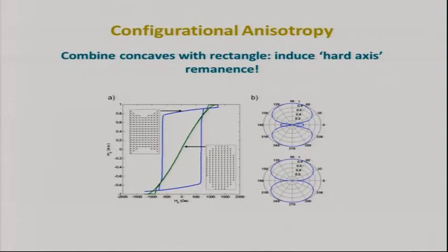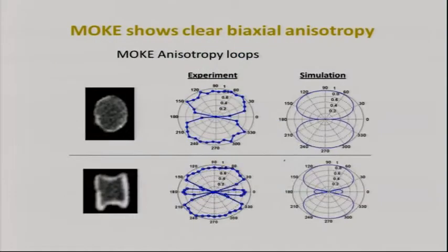Note that this is micromagnetic simulation. Note the steep switching threshold for putting the magnet right at the top of the barrier there. That is represented in this magnetic susceptibility polar diagram as these lobes. So in the normal rectangular nanomagnet, we just have an easy axis up and down. Here we've introduced a little bit of easy axis along the short direction. And in fact, we've been able to demonstrate experimentally that this works.